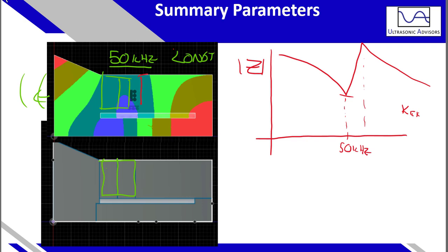So if we had actually shifted this, and we'll draw this in red, if we had our stack right here instead of at the original position, and we moved it there, what would happen? Now the piezo is no longer in the highest stress location of that transducer, correct? So the effective driving becomes less.